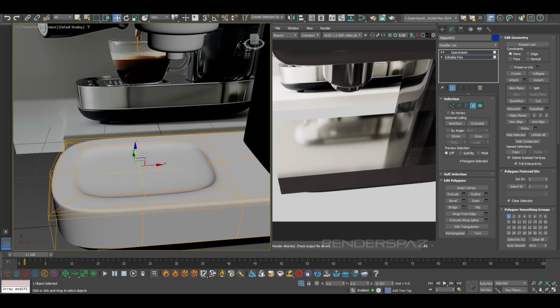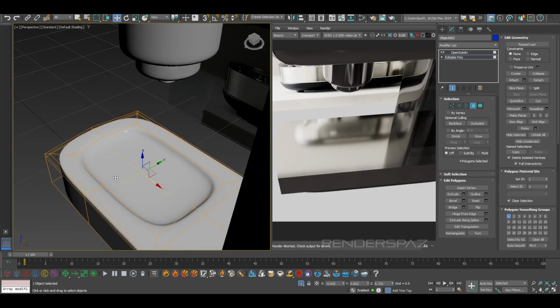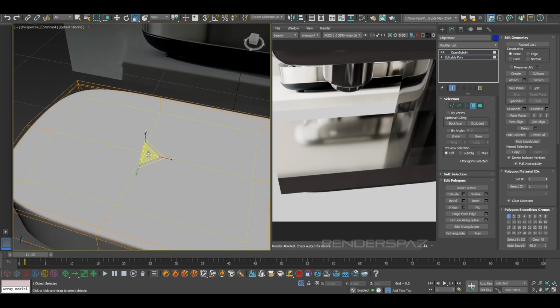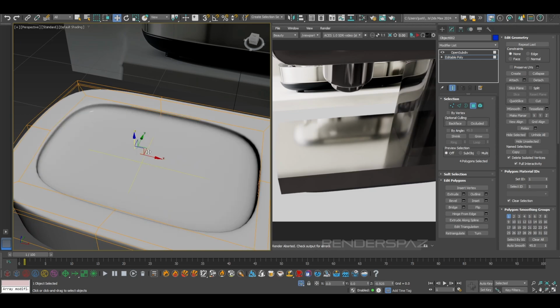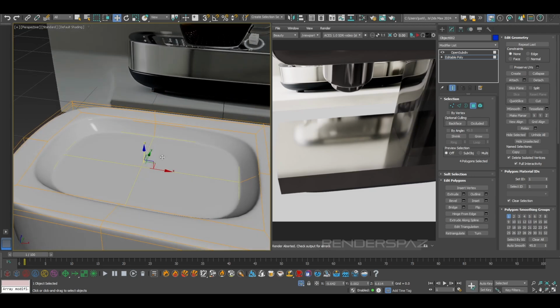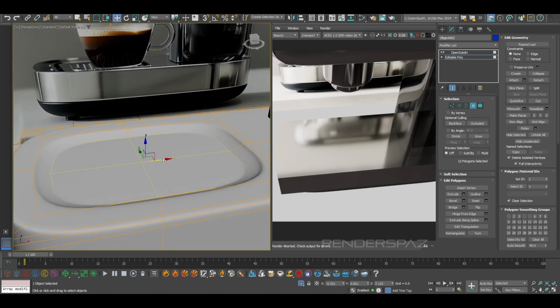And we're just going to hold shift and drag in on the Z. So we start to get a little bit of a dip. Let's see here. So you might want to just hold shift, drag in. Just want to have an edge there. Right, so now that we have an edge, I'm gonna hold shift one more time. And what I'm doing is pretty much beveling each of the edges as I'm extruding down. This way we're gonna get some sharpness to the corners here.